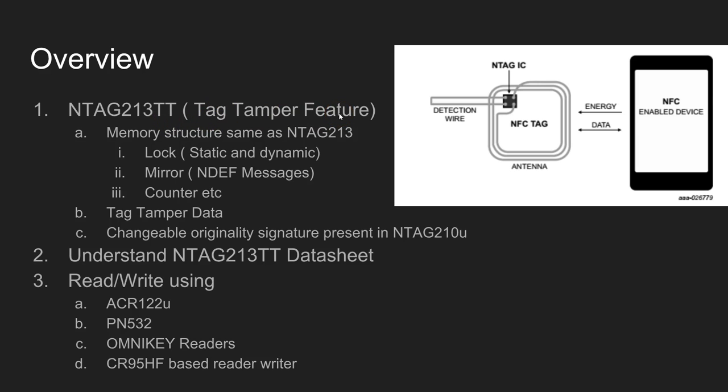What it basically means is, this is an example block diagram of this NFC tag. If you look at the diagram, you have the antenna here, which picks up the power from the RF reader writer. It is this bit here. The tag monitors this connectivity, and if there is a break in the connectivity, the break may be because somebody has pulled this tag.